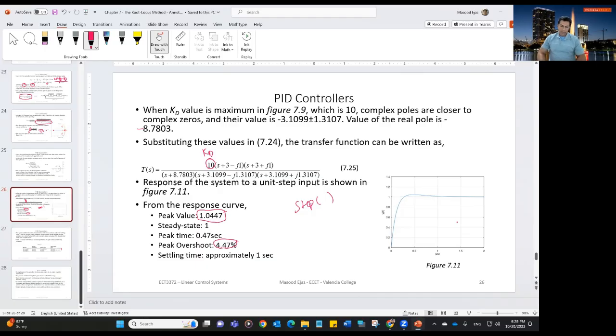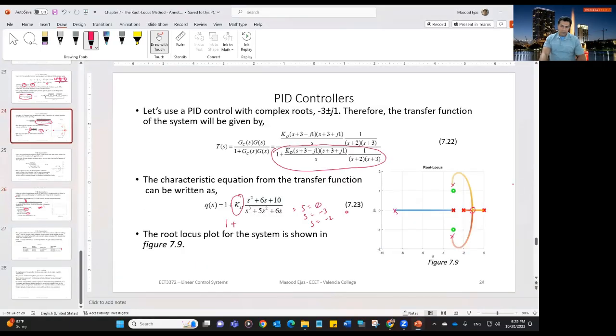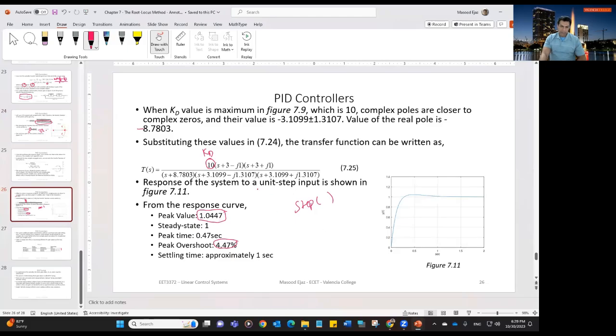But again, for manual tuning, of course, you go with the Root-Locus, use the values from the Root-Locus for the value of KD, calculate the KI and KP, plot the response first, and then choose a desired value of KD that can give you the desired output response. And then you can calculate the values of KI and KP for your control system from that value, as I explained.